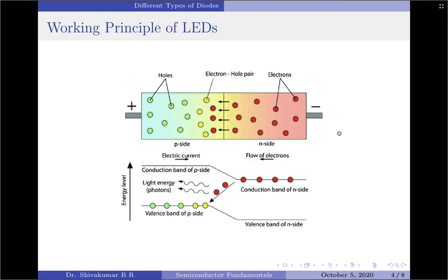This effect is called electroluminescence, and the color of the light, corresponding to the energy of the photon, is determined by the energy band gap of the semiconductor. The material used in LEDs is basically aluminum gallium arsenide. In its original state, the atoms of this material are strongly bonded. Without free electrons, conduction of electricity becomes impossible here.